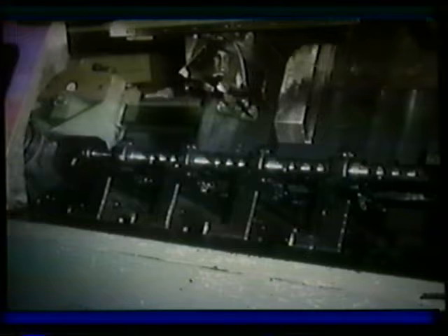Another straightening step follows heat treatment. After straightening, the journals and cam lobes are finish ground. This is a precise machine operation in which the cam lobes are ground to specifications of plus or minus thousandths of an inch.